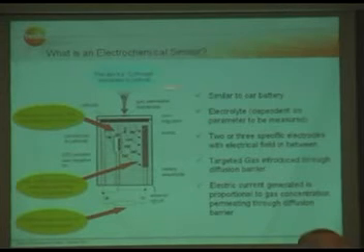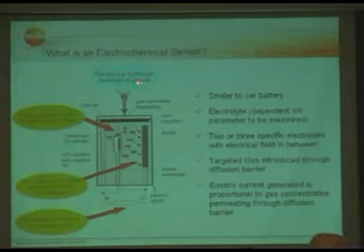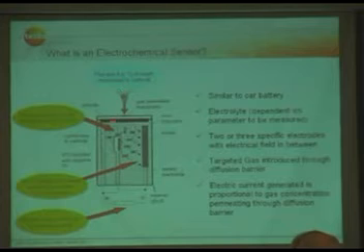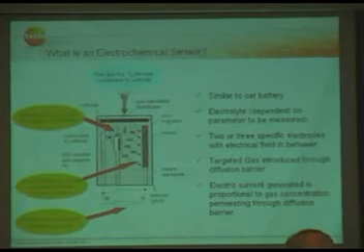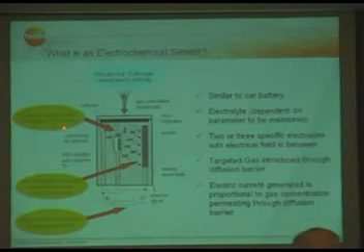What happens is the flue gas, like O2, gets into the sensor through the membrane, and then it gets to the cathode. As soon as it's in the sensor and in this electrical field, OH ions will be created, and they will migrate to the anode.